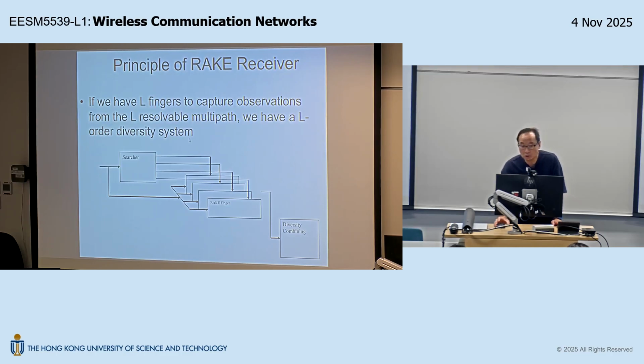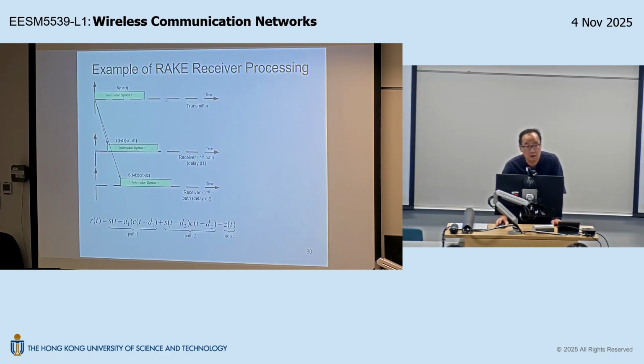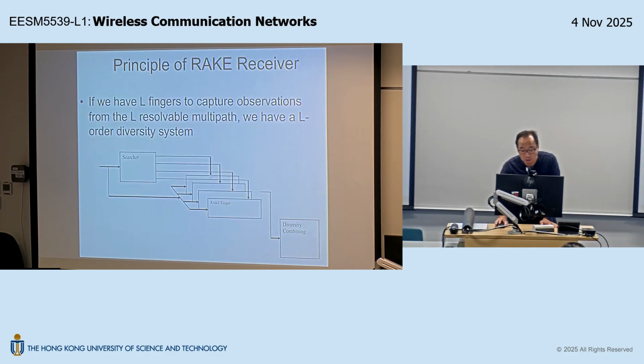And then we also talked about interference suppression for the second type of interference, that is the inter-symbol interference, right? Because we have multiple resolvable paths, it will be interfered by the echoes of the previously transmitted symbols, and that will cause the irreducible error floor. We also illustrated that by spreading and despreading, according to one of these despreading timings, we will be able to suppress the interference and reduce the error floor. So that was the rake receiver architecture.